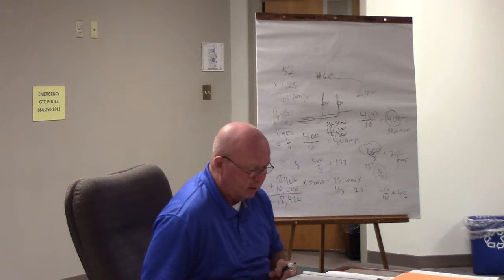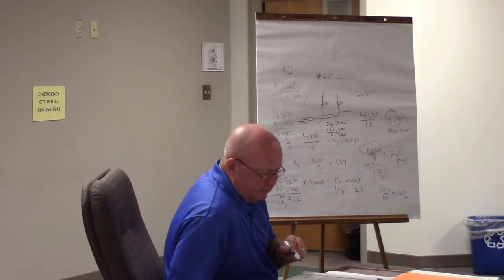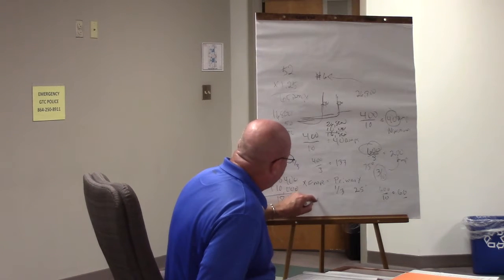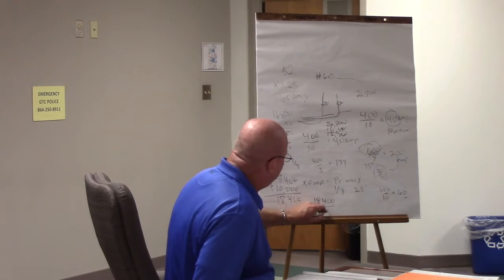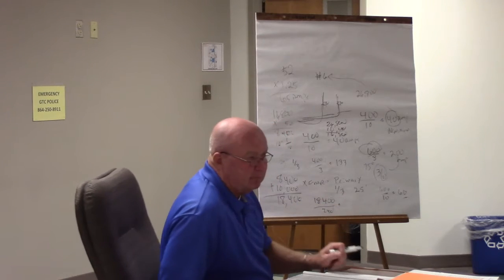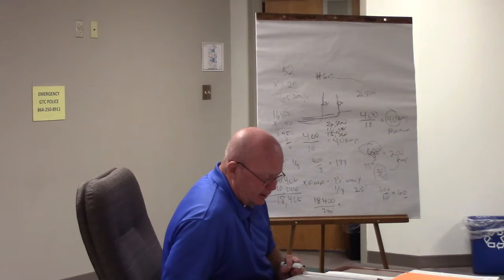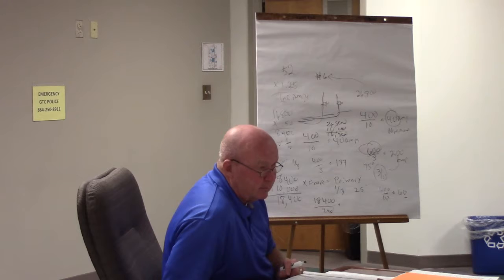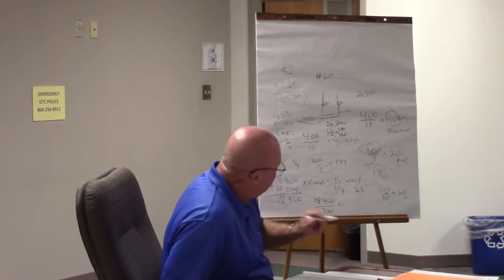Or if you really wanted to get down, let's say this is 120/240. We'd find out how many amps it is by 18,400 divided by what? 240, wouldn't we? And how many amps would that be? Just to do it, just curiosity. 76.